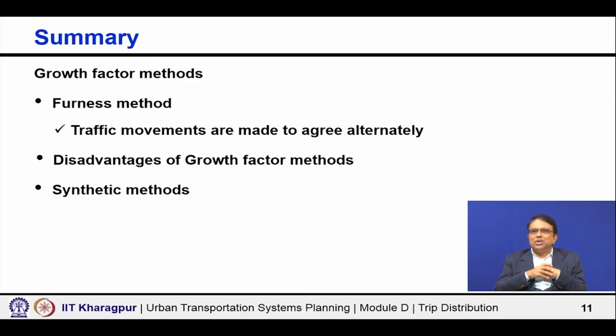But in between, if the city has got a metro, say you did the studies before the metro was operational, and now in the last 1 year the metro is operating along the length and breadth of the city. Even if it is 6 months or 1 year, still you cannot use the growth factor based method, then you will be wrong. So, it has the potential, it has the limitation. You have to judge where you can apply it advantageously and where you should not apply.